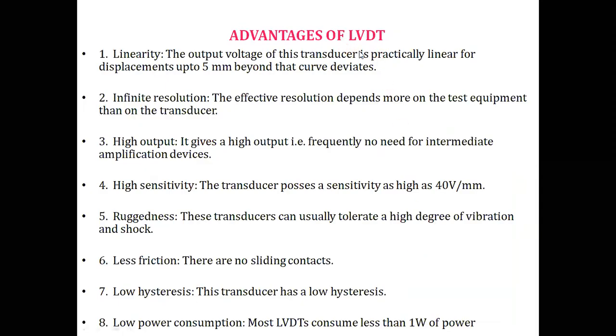And the advantages of LVDT. First one is linearity. The output voltage of this transducer is practically linear for displacement up to 5 mm. Beyond that the curve deviates. Infinite resolution. The effective resolution depends more on the test equipment than on the transducer.